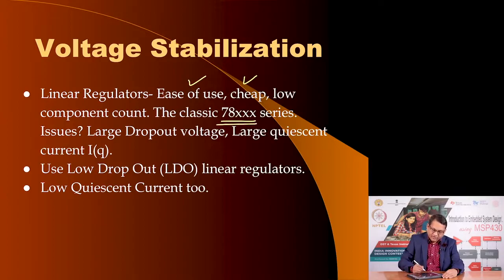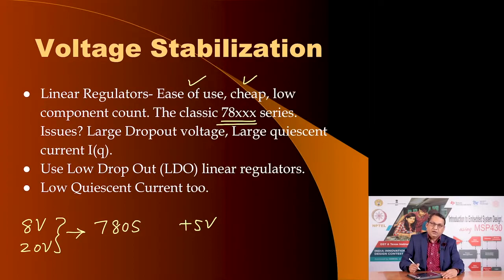For example, you may have used a 7805 in your electronic circuit design, and this provides a plus 5 volt power supply when the input could be anywhere from 8 volt to more than 20 volts. So, you can provide this as the DC voltage, and this regulator will give you 5 volts. And there are many other output voltage options available. 5 volts is one of them.